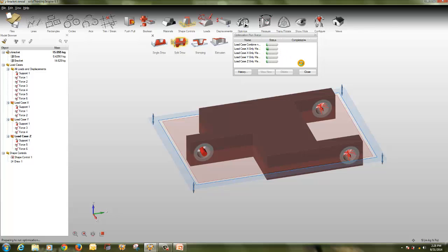So now you can have parallel solving, and it will solve all the load cases. You can put them back to back, but the point is, you should have a good machine to solve these back-to-back load cases, and also a power backup, because if it shuts down, it may crash, and you cannot restore the run while it's solving.